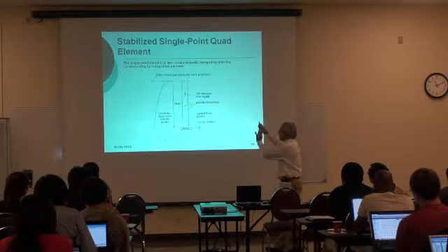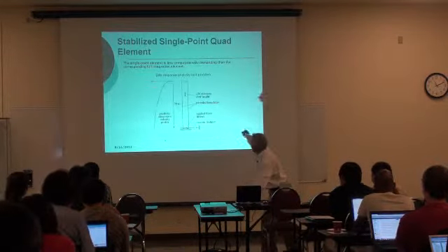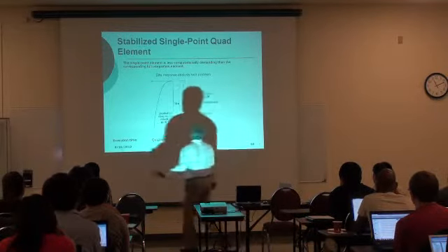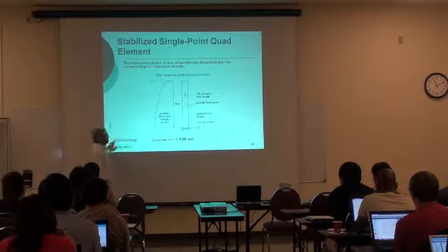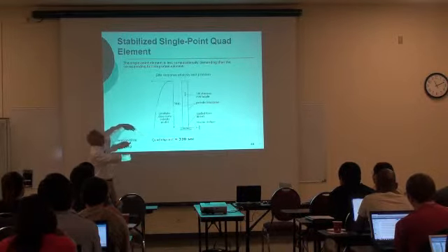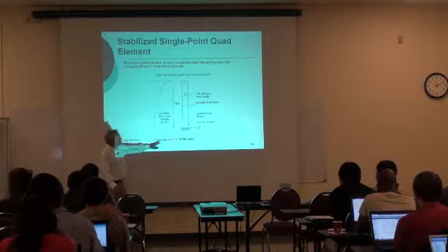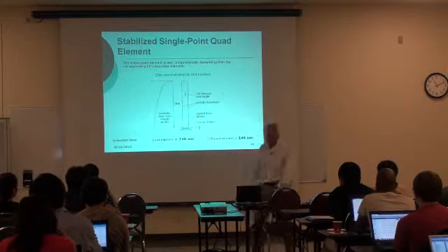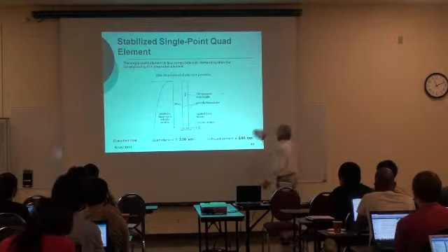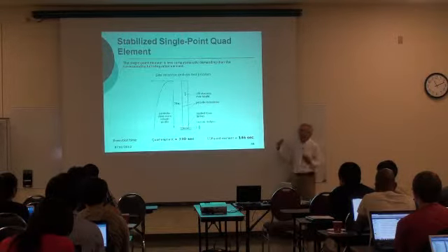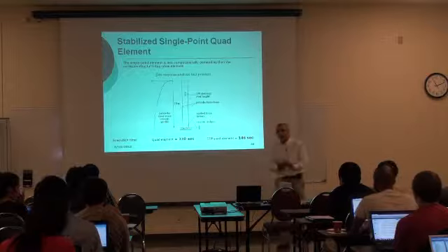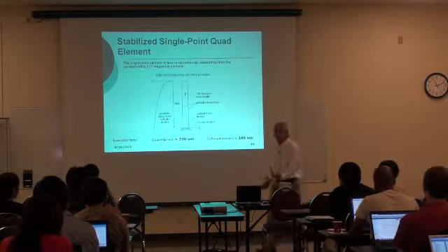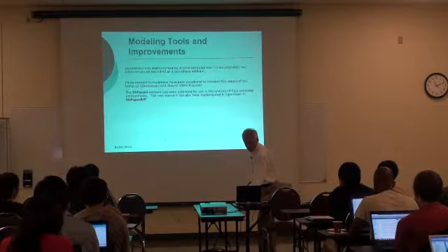Let me show you, we did a free field analysis, a total stress free field analysis. Using the quad elements, the execution time for that particular problem, with 150 elements, was 330 seconds. When we use the stabilized single point, we reduce that to 146 seconds, almost half. So that's a benefit that you can get. So I recommend using it. Try to use it because it's available and seems to be giving very good results.